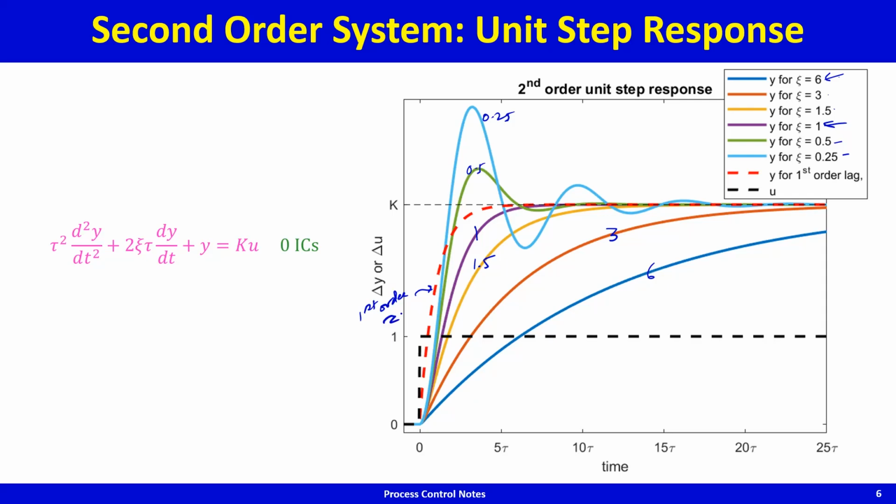And you can see the first order is actually the fastest, second order is slower. Second order can have oscillations if you have an underdamped system, and as the damping coefficient decreases, the response becomes faster and faster. However, as you become too fast, the critical damping case is the case where you get no sine term. So, non-oscillatory response. After chi goes below 1, you start getting the sine term in y(t), and that is the source of these oscillations.